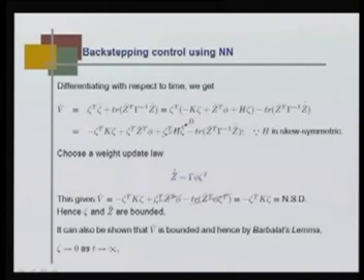You see that due to skew symmetry, this quantity becomes 0, and if I assume z hat dot is this quantity, and z is actually the weight vectors. So, if the weight update law is taken by this, then this quantity and this quantity are the same. So, V dot is simply xi transpose k xi, and k is a positive quantity, and hence this is stable.